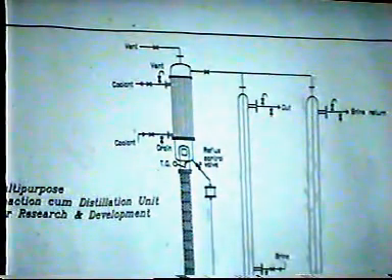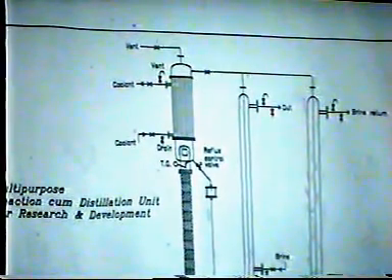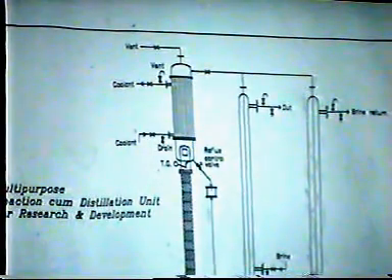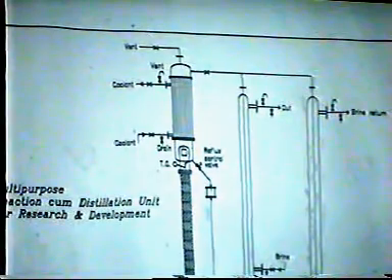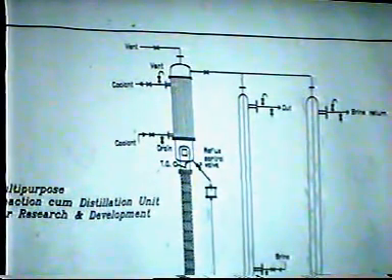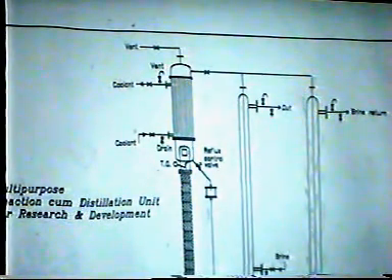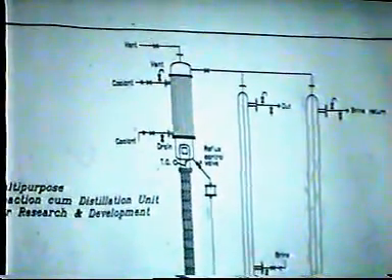Vapor trap vent, which indicates whether the condenser is performing well or not. Now we have a special venting system here, which is also externally cooled. Now this is for if that condenser water is not circulating inside that, or some kind of airlock is there in that, then one would not know at that height whether the condenser is performing well or not, or the boil-up rate is higher than the condensing capacity.